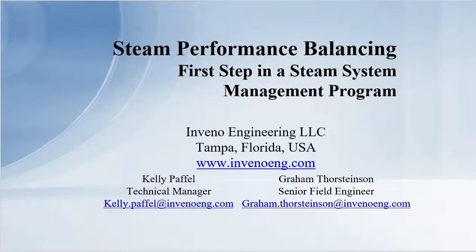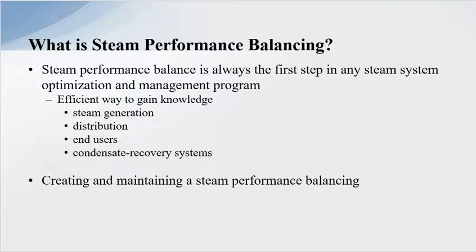Today, I'd like to talk about steam performance balancing, really the first step in steam system management programs. First thing to ask is, what is steam performance balancing? Steam performance balance is always the first step in any steam optimization and management program. It's an efficient way to gain knowledge in the steam generation side, distribution, end users, and condensate recovery systems. Creating and maintaining a steam performance balance program is a continuous process.